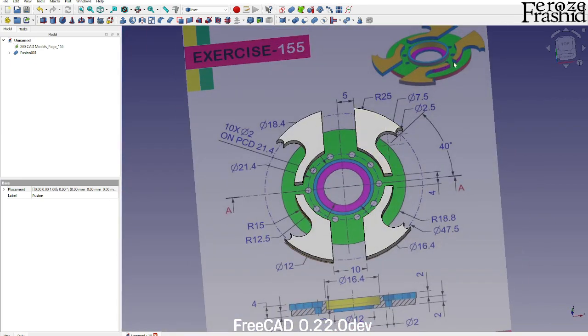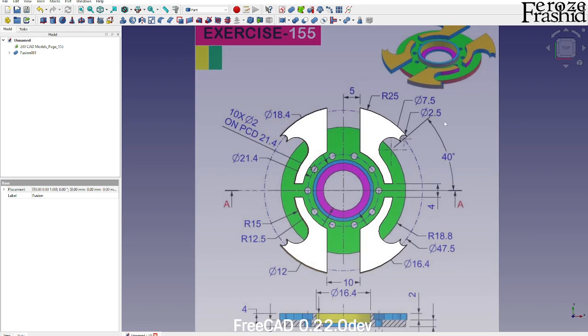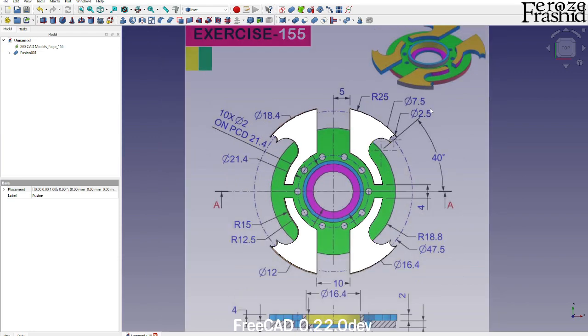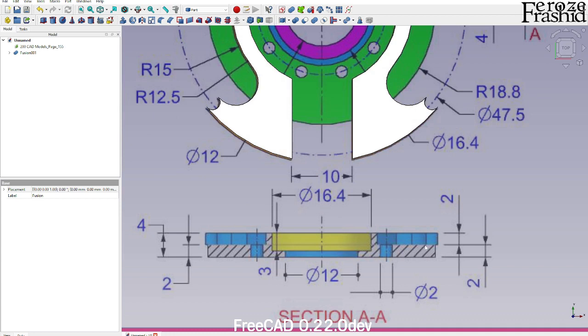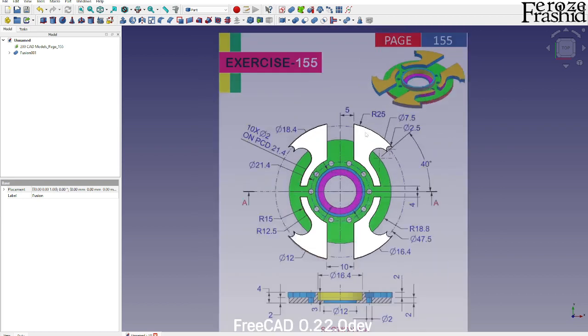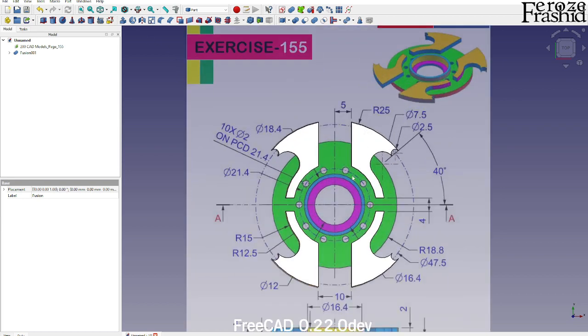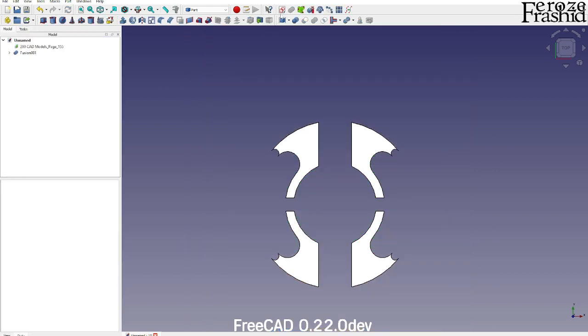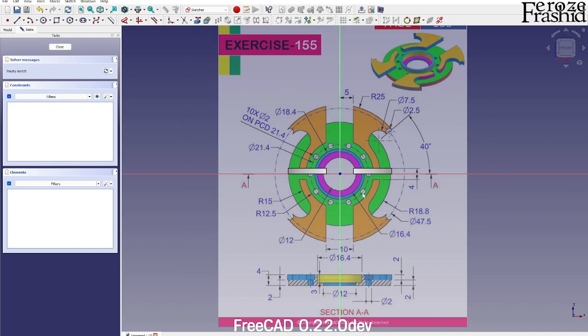Now, how about the base? Normally I start with the base. I don't know why I started with the wings, but we got that part done. Now on the base, we have one thickness here, another thickness up here, and then the third thickness here. So that will be 3 different cylinders, or like 3 different tubes. Or what I can do is place this image on the XZ plane and then draw a sketch on the XZ plane, right? And draw this. Okay, I'll have to relocate the image.